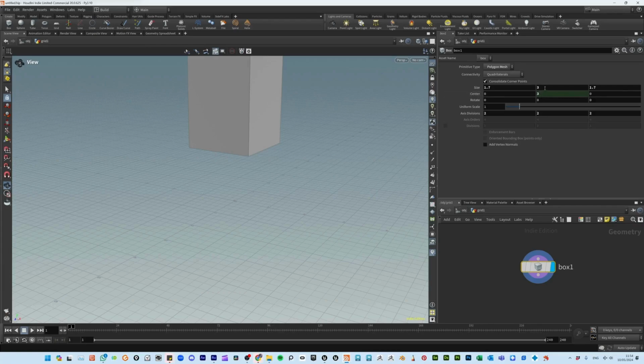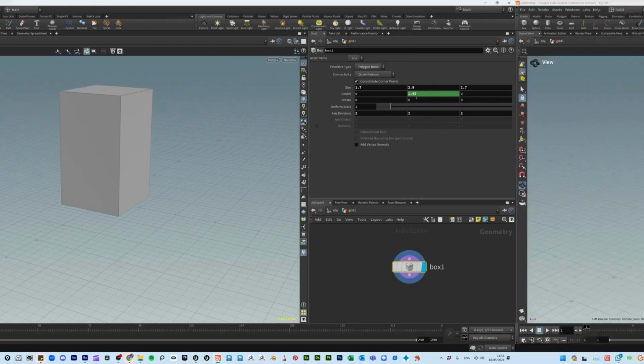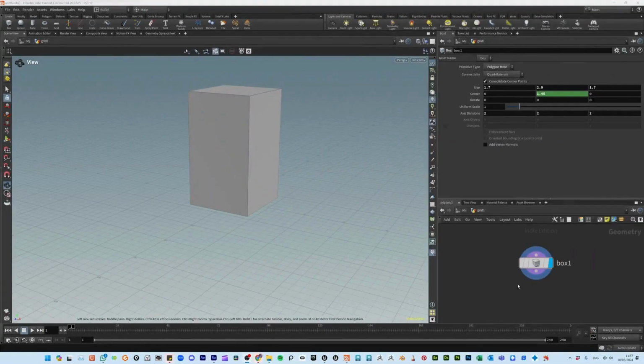Now this number refers to the same number 3. If I would like to have it half the size, I press here again and just add a small formula. This time it's divided by 2, press enter, and now every time I change the height, this number is being divided by 2.